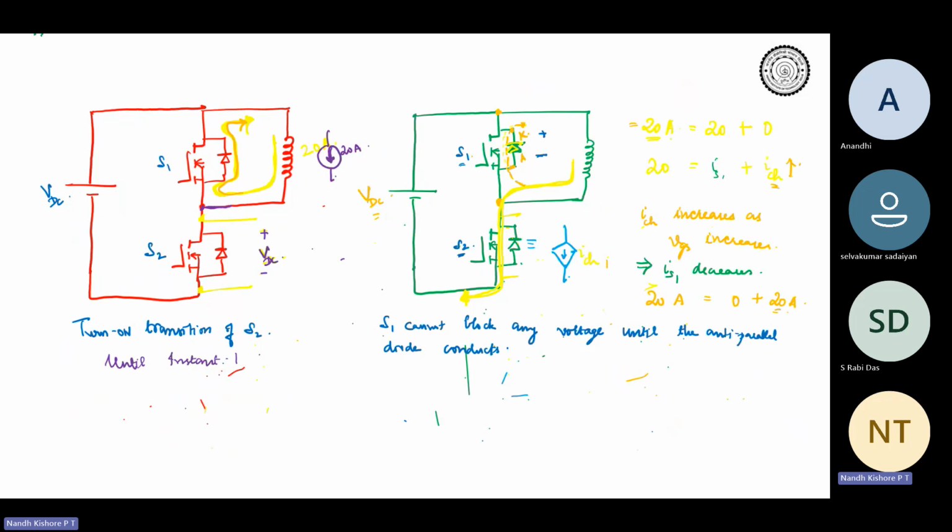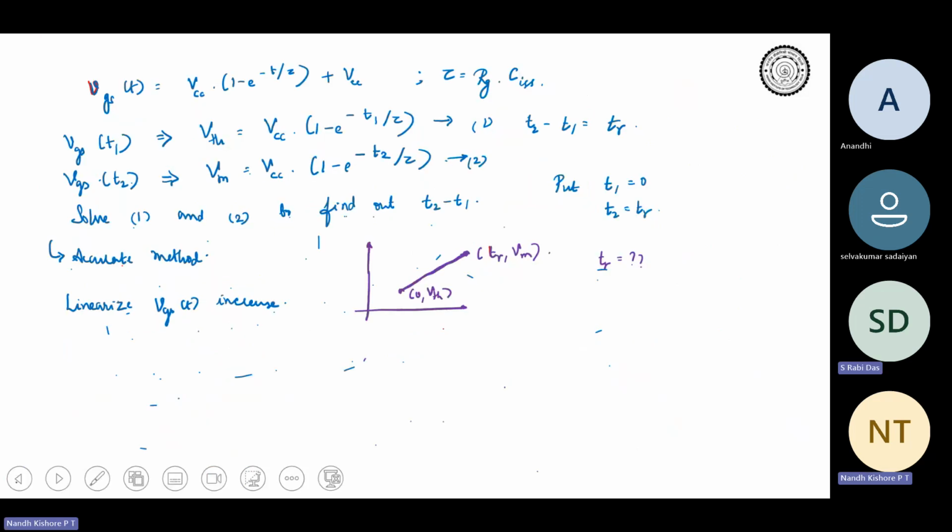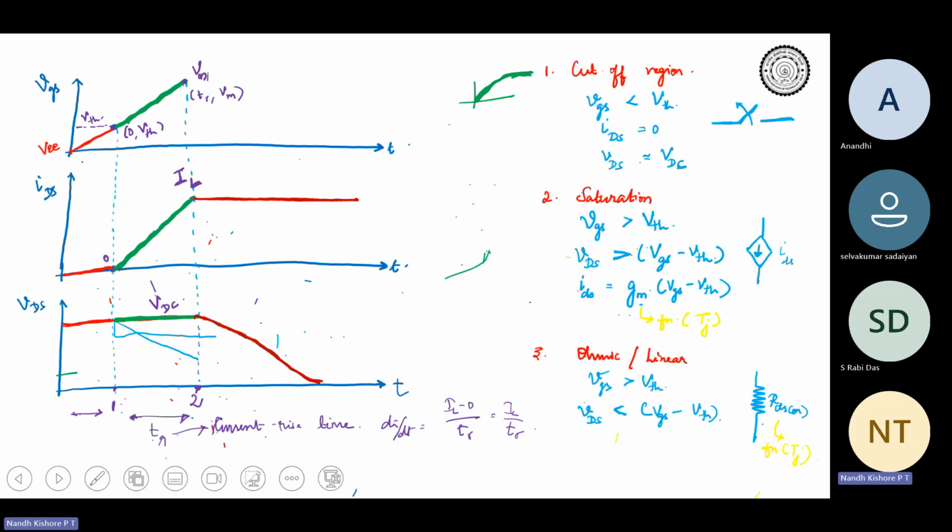If you are dealing with a half bridge network with a constant current source, you will see this because primarily you will see the diode conducting in antiparallel fashion. In that case, obviously, the diode cannot block voltage unless it stops conducting. So that's why you will see this profile. So to evaluate the losses, you have to take both of these intervals into consideration.